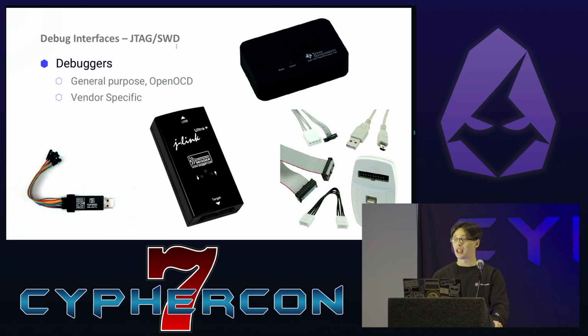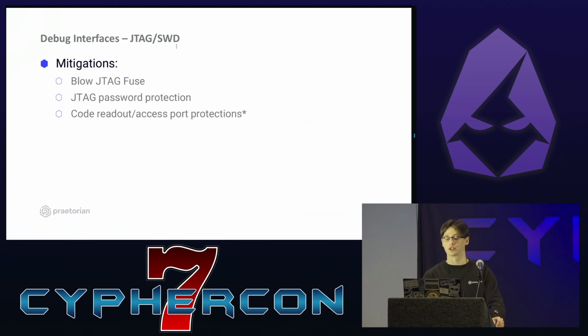It's great for a lot of cases and it's awesome to get you started, but as you get more serious, you may want to get some more of the manufacturer specific debuggers. On the top right is the TI, Texas Instruments MSP FET. That's great if you're working with MSP430 microcontrollers, so if you see those, that's a great option. And then at the bottom is the ST-Link, so working with STM32 processors, things like that.